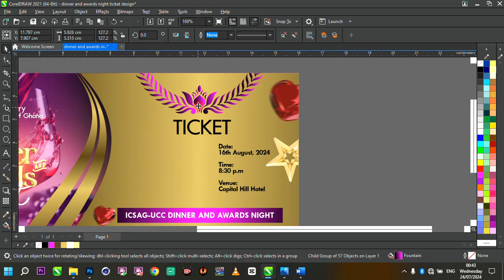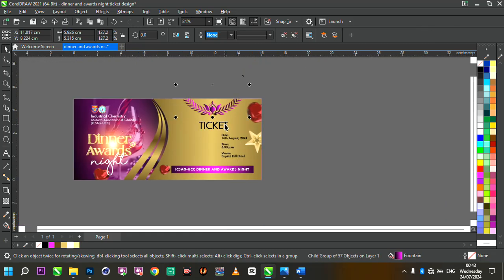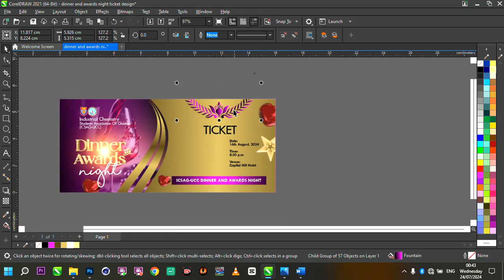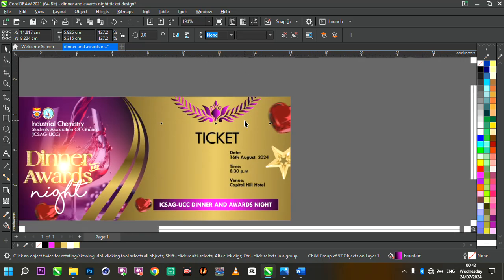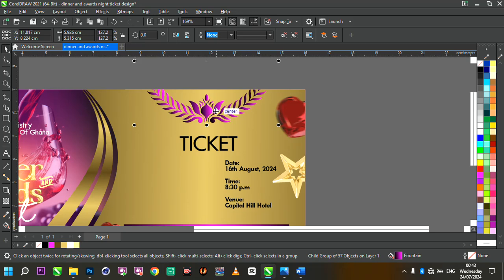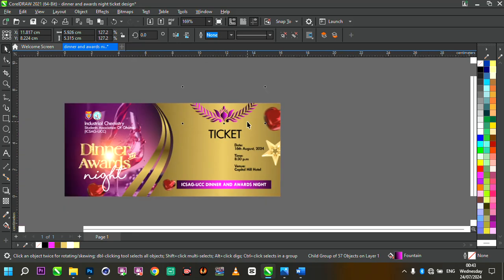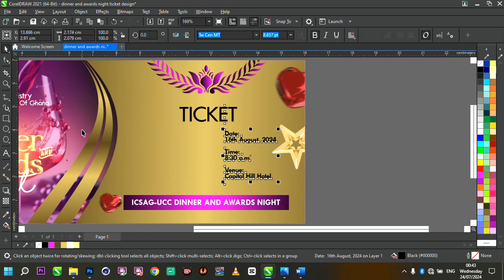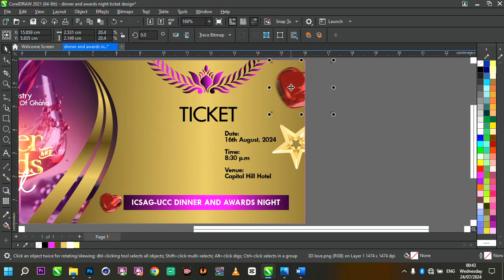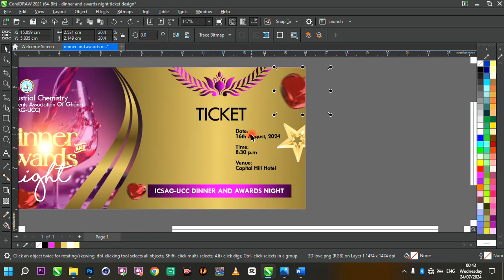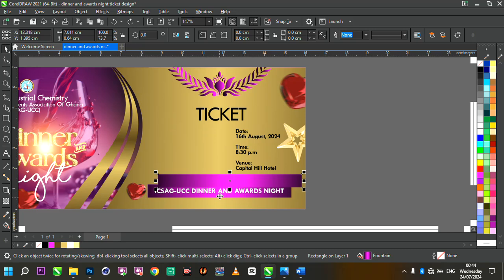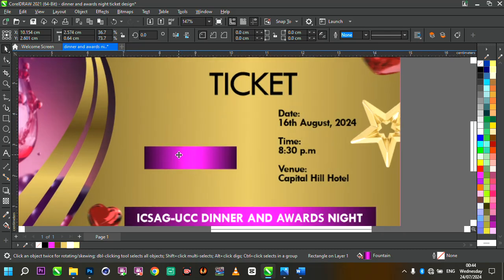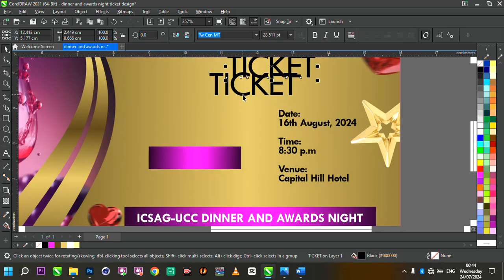Can push this up. Okay, to edit elements in the background without having to actually open up the power clip, you can hold down Alt and click on the object in the background, or any other object you've power clipped an item into. That should just select the object for you without actually having to open up the power clip, okay. Then you go ahead and make a duplicate of this as well. Reduce the size of this a bit. Position it right here. Make a duplicate of this.